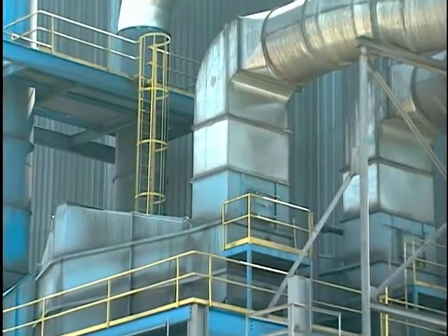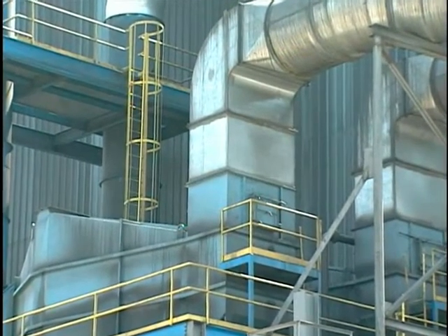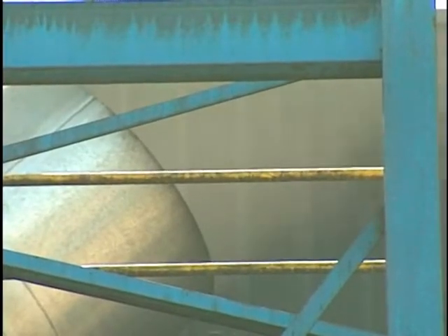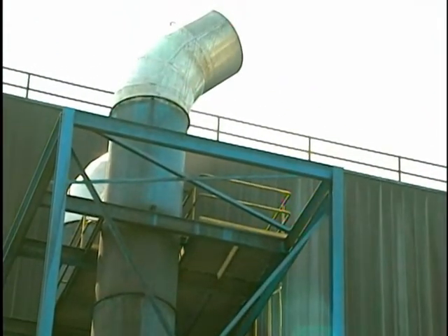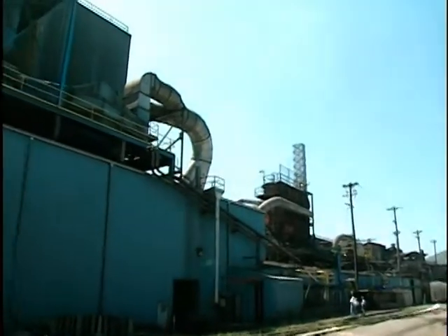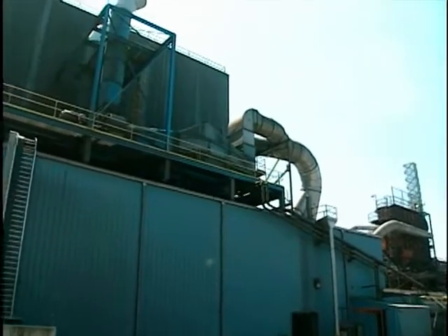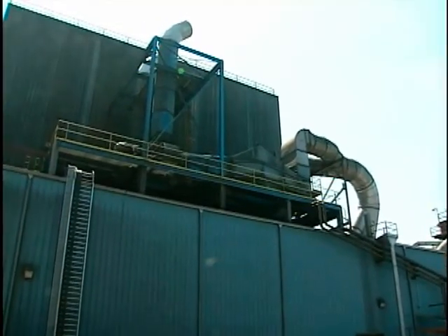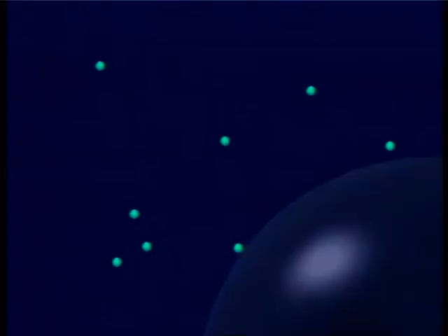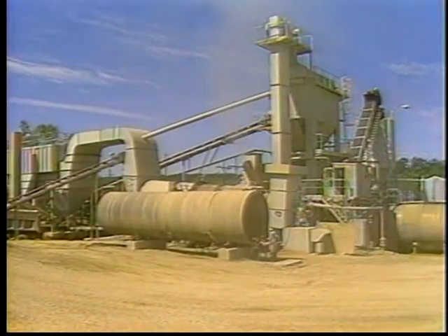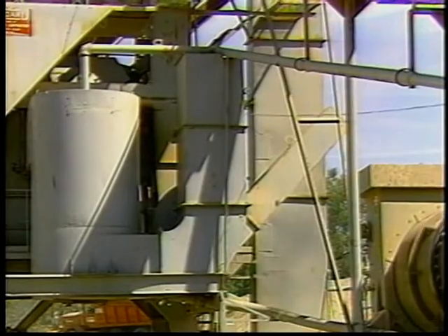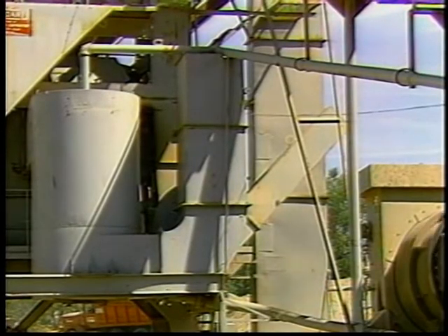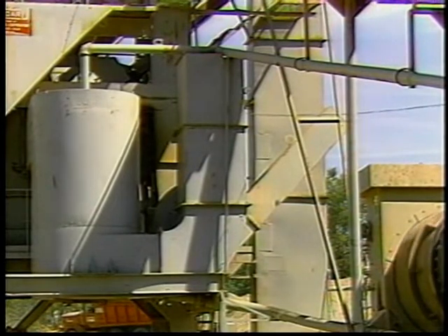Even though absorbers collect gases that cannot generally be seen, stack opacity is still a useful inspection parameter, although the presence of condensing moisture may make the observation difficult. Hydrochloric acid in most organic vapors can nucleate at high concentrations to form particles as the gas stream passes through the absorber. These particles are very small and are not efficiently collected. The presence of a visible plume usually indicates that the absorber is not functioning properly, since efficient absorption would reduce the concentration of the pollutants that can form particulate matter.